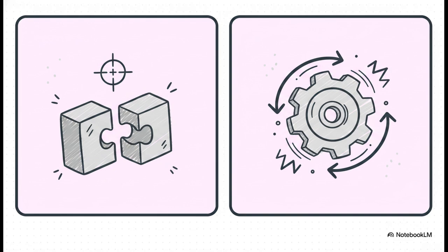Listen, one of the absolute most common and costly industry mistakes is using runout when true position is actually what's needed. If a part only sits statically in an assembly and never actually spins, applying a runout tolerance just forces the manufacturer into complex, expensive dynamic inspection setups for absolutely no functional reason. So remember, choose true position when you care about where a feature statically sits, but you absolutely must choose runout when you care about how a feature behaves while actively spinning.